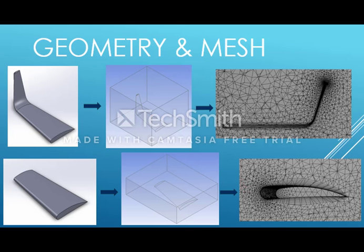The wing and winglet were downloaded from GrabCAD and imported into Workbench's design modeler. Inside the design modeler, the wing was placed in a rectangle representing the domain of the flow. A revolve feature was added to allow for multiple angles of attack to be analyzed. The wing was then subtracted from the domain to allow for a mesh to be created.